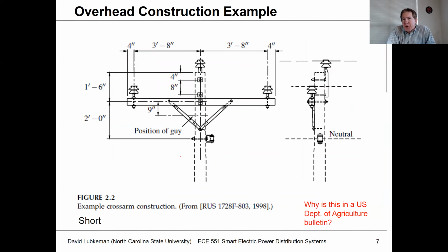What's going to be important in this case is what are the construction characteristics as far as the distances between the wire, because it's the distances between the wire that's going to define the inductive reactance of our overhead line. And so this is a construction drawing here. This shows kind of like you have a cross arm. You have these insulators that we're going to place the conductor on top of. So the conductor is going to be on top of here.